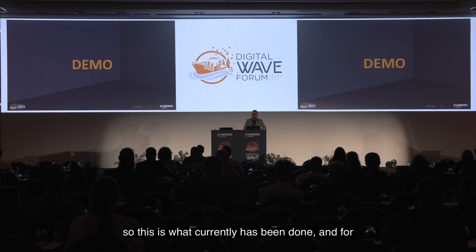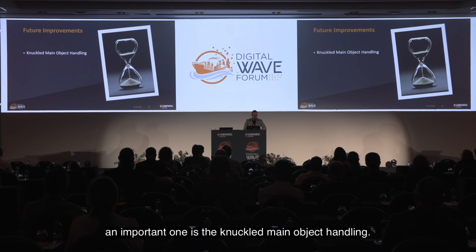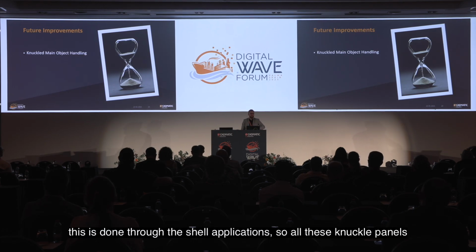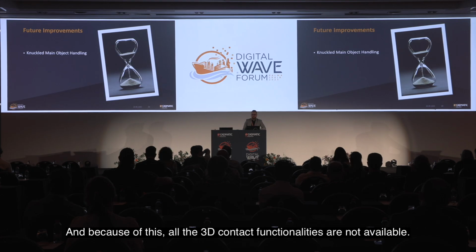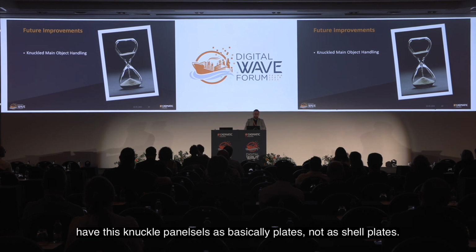Yeah, so this is what currently has been done, and for the future we have just the main topics. An important one is the knuckled main object handling. Currently this is available in the integration, however, this is done through the shell application, so all these knuckled panels are imported as shell plates, and because of this, all the 3D contact functionalities are not available. So for the next release, we are planning to have these knuckled panels basically as plates, not as shell plates.